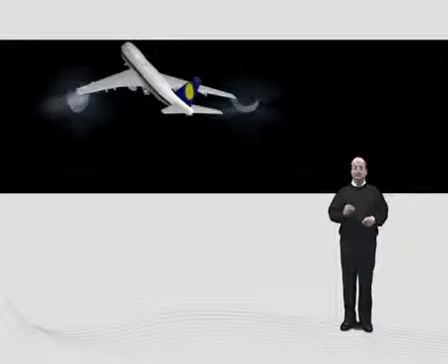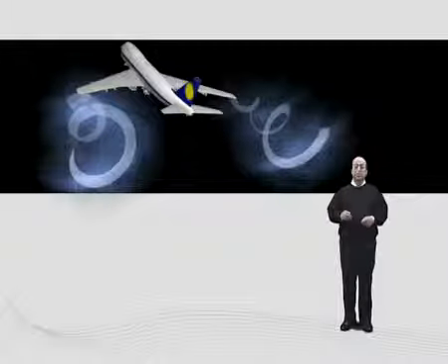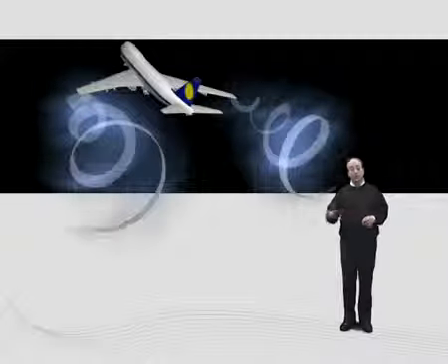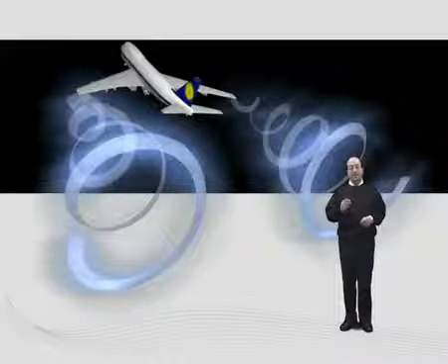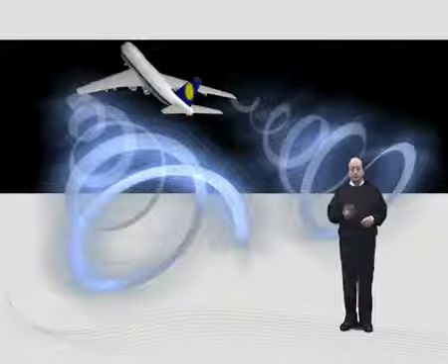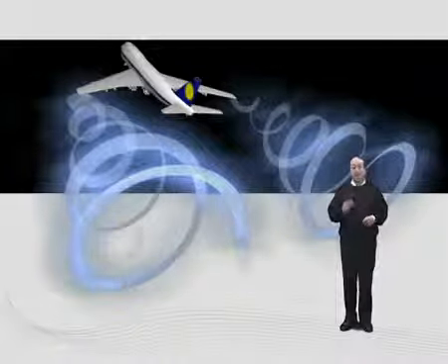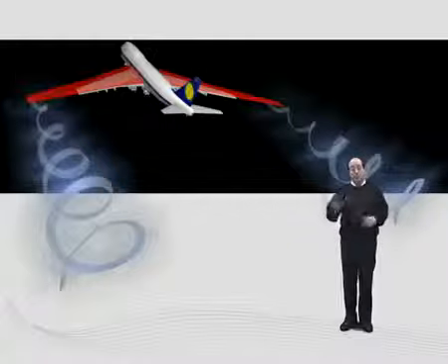The circulatory motion around the airfoils creates two big vortices at the wing tips, which detach from the wing and tend to roll up downstream, forming two vortex cores. The intensity of these vortices is higher for low aspect ratio wings and for high lift coefficient.